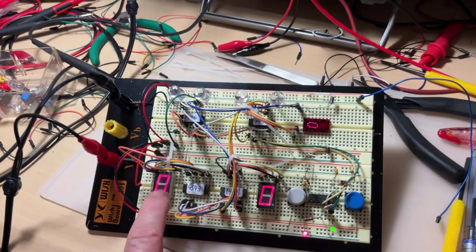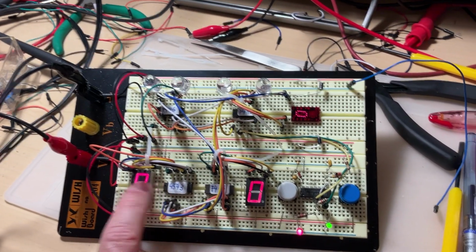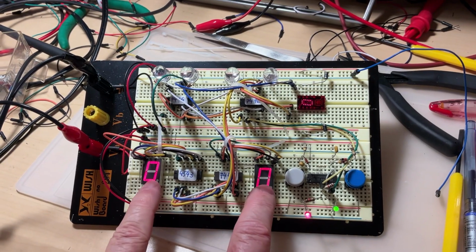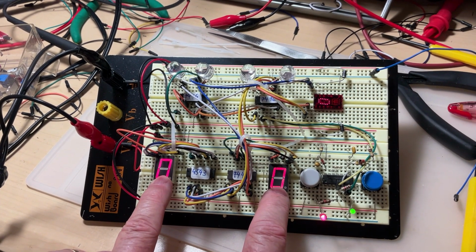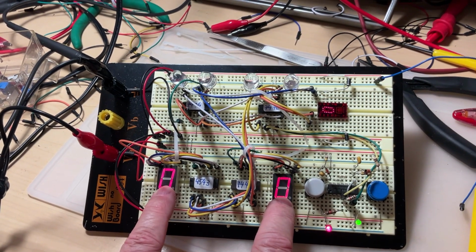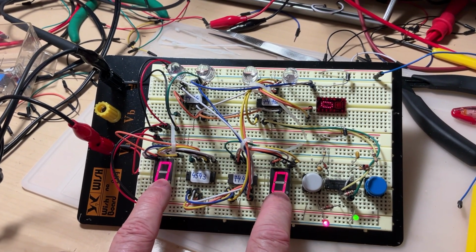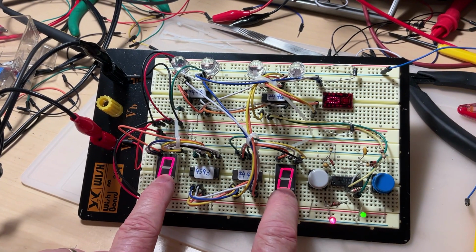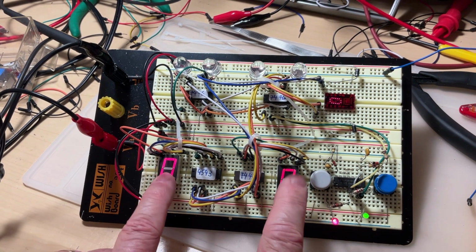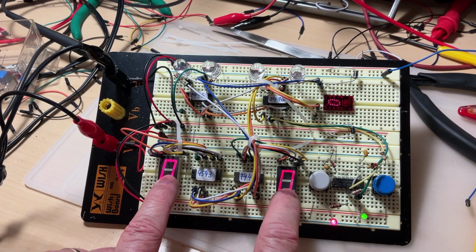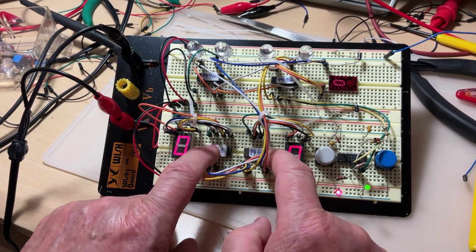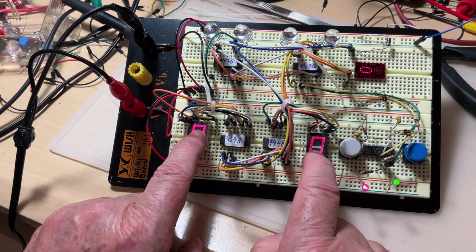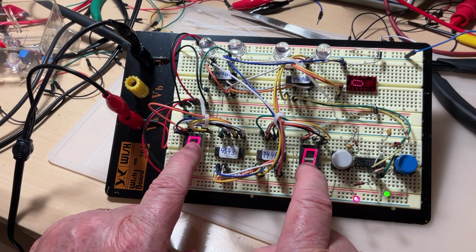So we identified here that this particular decoder is attached to the digit, and by the way, the two digits I have here are identical, because I used Common Cathode displays. Their code is MAN 6780. And these two are identical. But the reason they don't show the same thing after 9 is not because of them, it's because of the decoders attached to them. So you see the difference now.